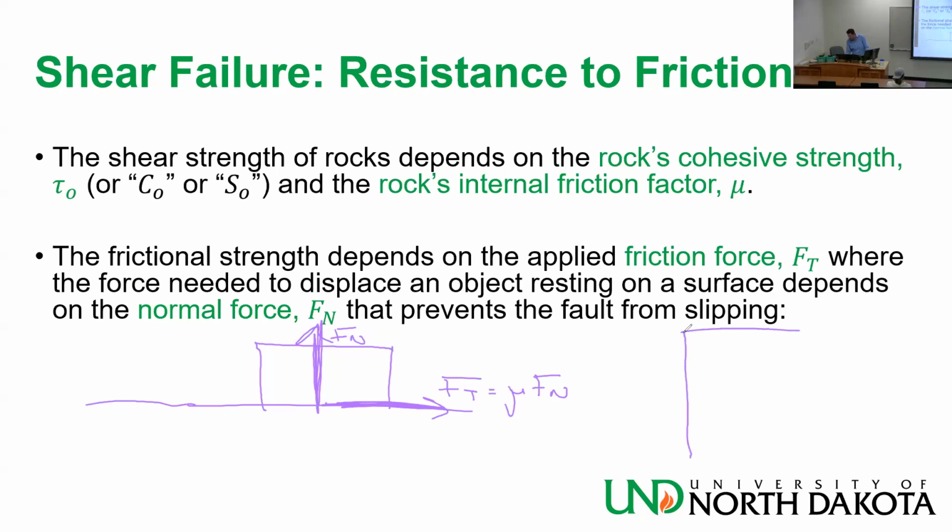Now I have this piece of rock, and I have this sort of fold, a line of weakness, a bedding of weakness at the angle at which it wants to fail. And there is a reason behind that. Because in the Earth's subsurface, we have what we call the critical faulting stress hypothesis.